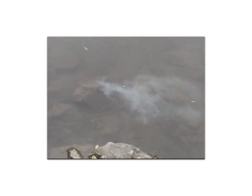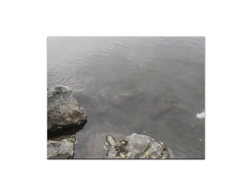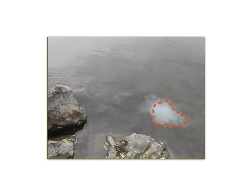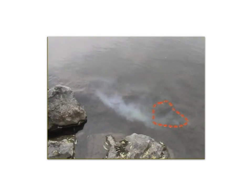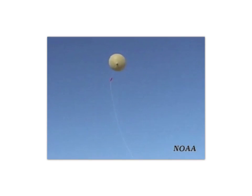Here, the blob of white water is followed as it moves downstream. But if we mark the instantaneous boundary of the blob of fixed mass at a certain time, then we can watch the water flow through this boundary while the original white blob flows on. This is the Eulerian approach. The Lagrangian approach works best, for example, in meteorology, where a weather balloon drifts along with the prevailing wind.